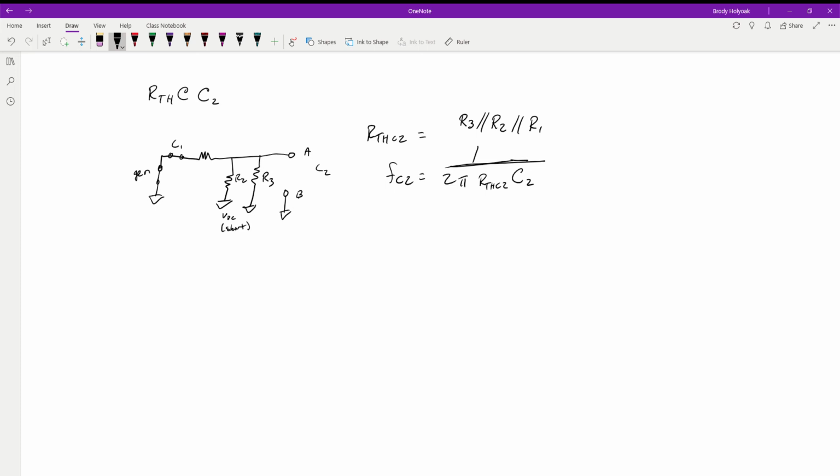Then the next step is we have one last frequency to solve for, because this is going to give us our max voltage out. So we call this one our F middle. F middle is very easy to calculate. You take your critical frequency 1, multiply it by your critical frequency 2, and take the square root. Again, the reasoning behind this gets into some of the deeper calculus, and honestly right now I don't need to go into that.